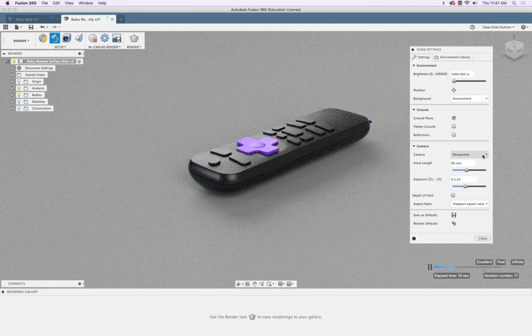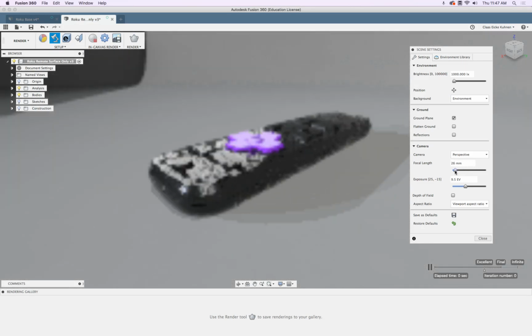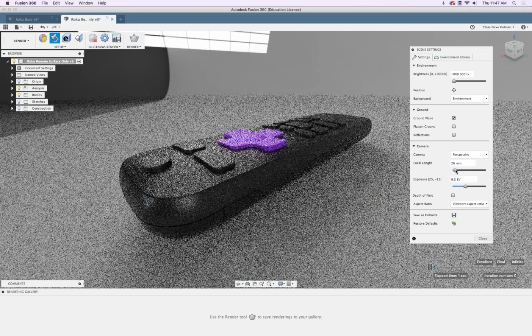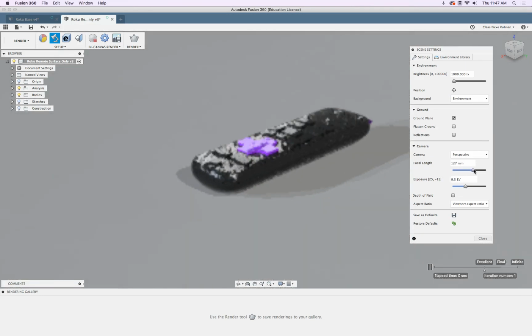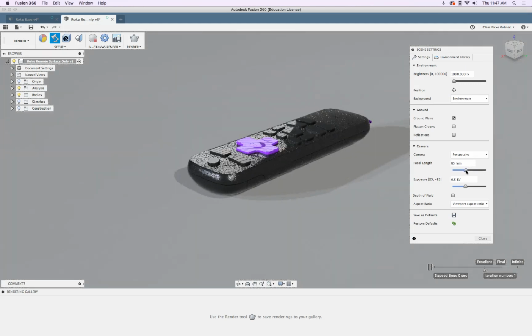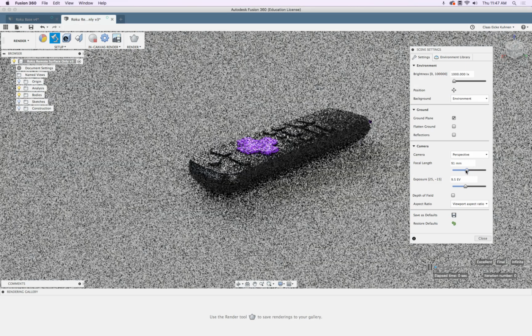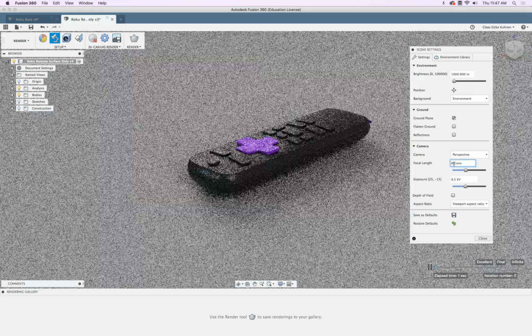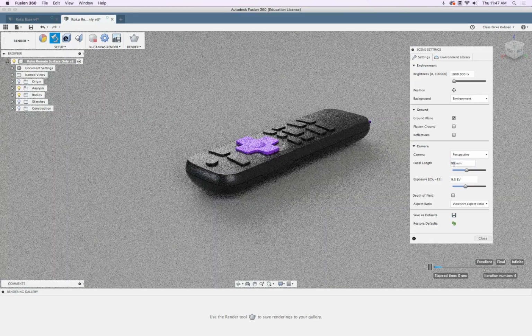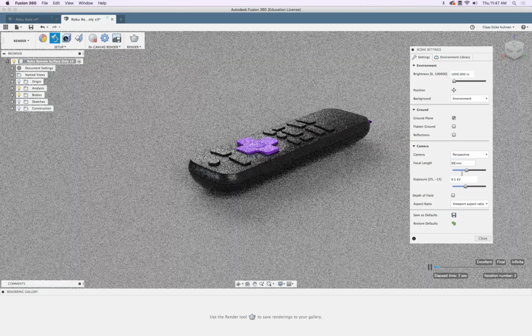With perspective, we can switch between orthographic or perspective view. We can change the focal length. So right now 90, this is more like a tele lens. If I set this to 25, you see this is more like a fisheye wide angle lens. 200 is nearly like a 0.1 orthographic perspective. 90 is okay, so very often I use values between 75, 90, etc.